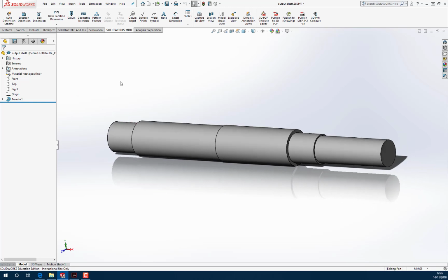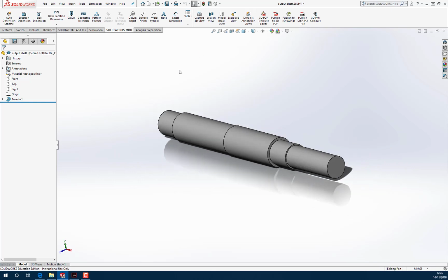So it doesn't matter whether you apply the dimensions first or the datums. Okay. In this case, I'm going to provide all the diameters where they are features of size. So that's this one, this one, this one, this one. This one is not a feature of size, so I'm not going to worry about putting the diameter on there or a fit on it. I'll just control that surface with a profile of surface later on.